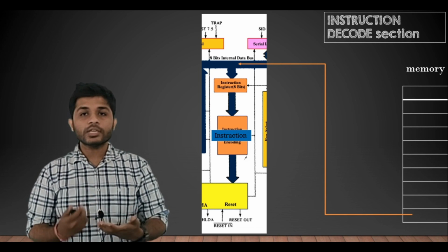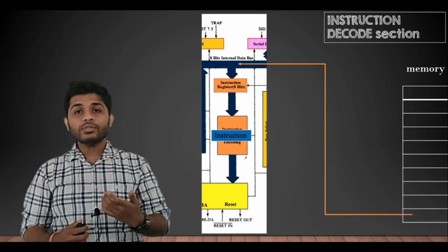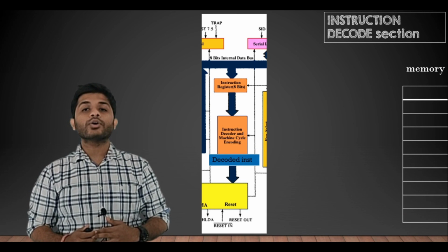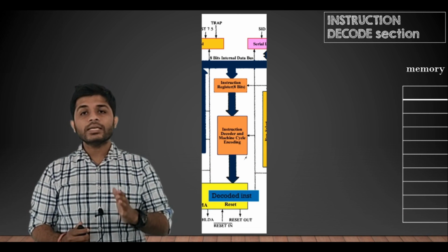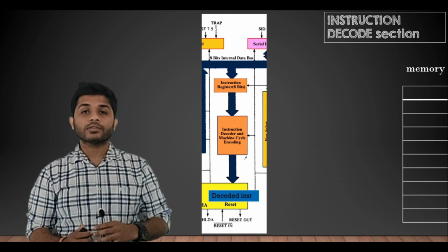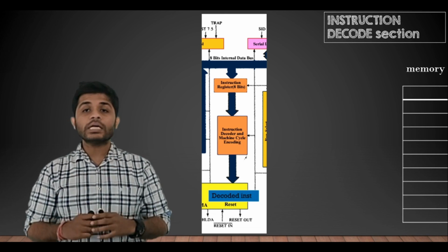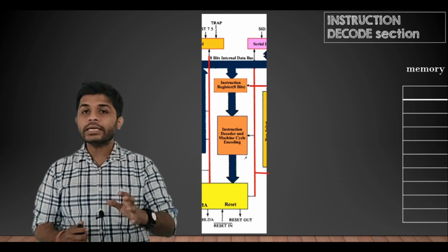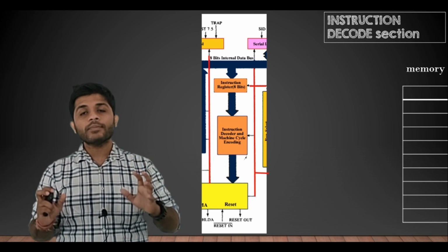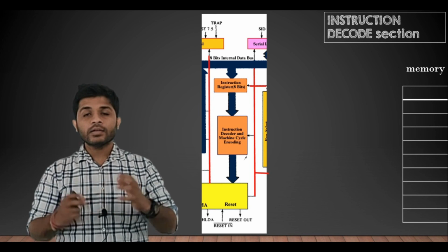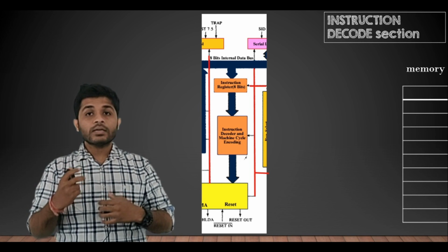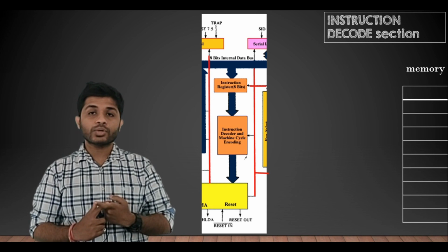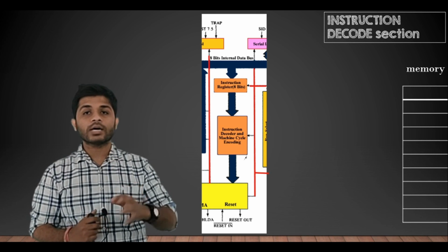After the instruction is decoded and the processor knows how many machine cycles are required, the decoded instruction is passed to the control unit. The control unit is connected to different blocks within the microprocessor. So when the decoded instruction arrives at the control unit, the control unit sends different control signals. By these control signals, different blocks within the microprocessor perform some tasks, and together the instruction is executed. So to fetch, decode and execute one instruction, these blocks are used.